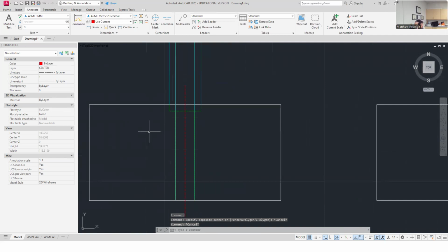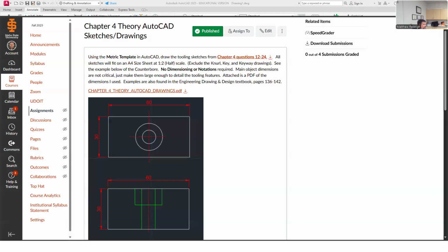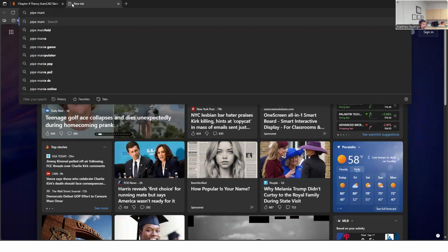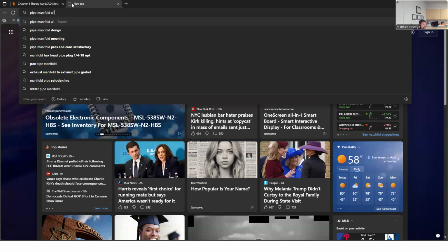But what a spot face is, I think of, I don't know, a coupler, usually for alignment. Usually a machinist will put a spot face in to help locate something quickly, and so the depth of it is usually quite shallow. Where I think a spot face would be needed, I think of a pipe manifold with couplers. These are all mechanical.